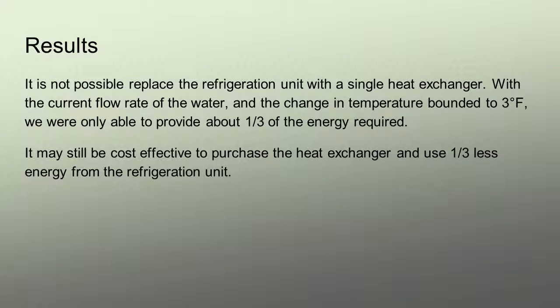The results gathered from the Aspen program let us know that it is not possible to replace the refrigeration unit with a single heat exchanger and our current constraints. We are only able to provide about 1/3 of the energy required. It may still be cost effective to purchase the heat exchanger and be able to use 1/3 less energy from the refrigeration unit though.